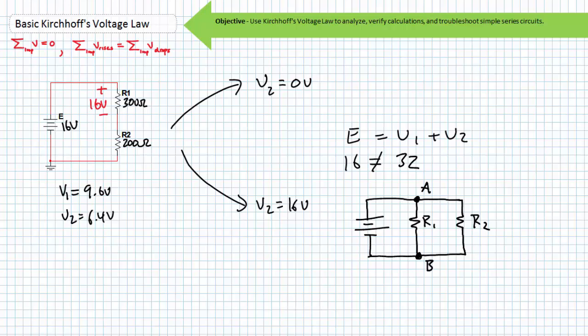In this circuit, there exists only 2 nodes, and both resistors and the voltage source are strung between them. Given the source provides a 16-volt rise from node to node, it is easily noted that there exists a 16-volt drop when you complete the loop. And here is where it gets interesting. Regardless of which loop you travel, R1 has a 16-volt drop, as does R2. Pause to consider the ramifications of this simple observation. Elements hooked in parallel always have the same voltage across them.